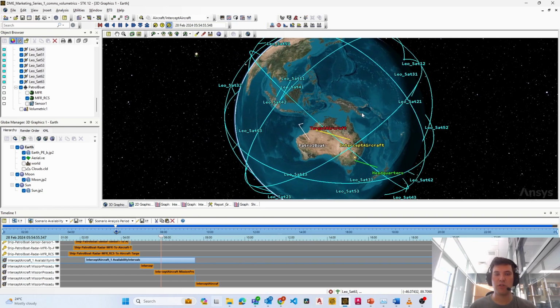So in this case, we've got 2 satellites per plane. There's 6 planes, and they're all equally spaced at an inclination of 45 degrees. And I've just created that constellation within STK using what's called the Walker tool. Now, each of these satellites is equipped with a hypothetical transmitter and receiver.